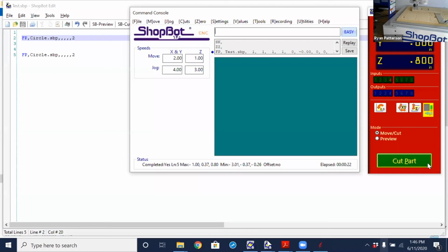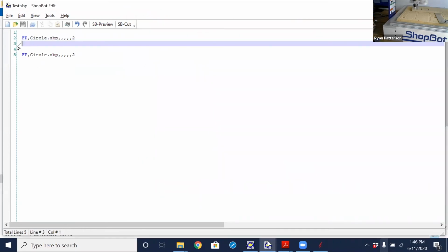And it didn't worry too much about where it was that I had initially set the location of 0, because you notice it's out in -2 inches. So if I want to cut a series of holes that are 3 inches apart, in between each call to this file, I could type in mx, comma 3.